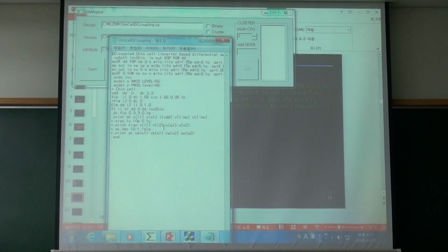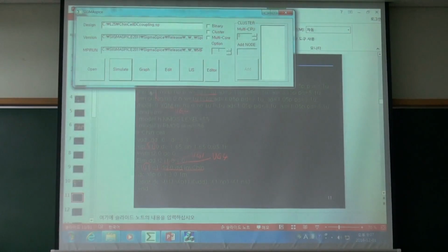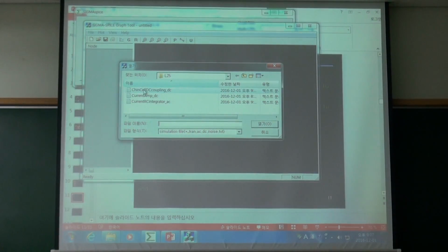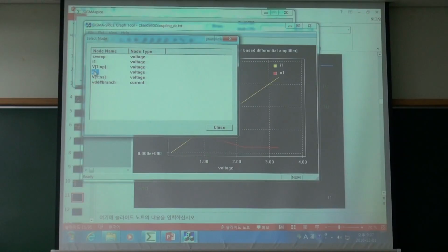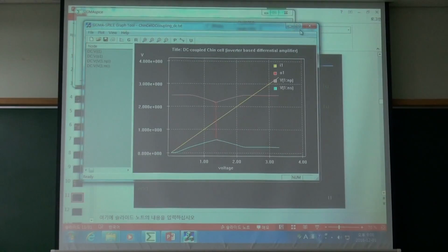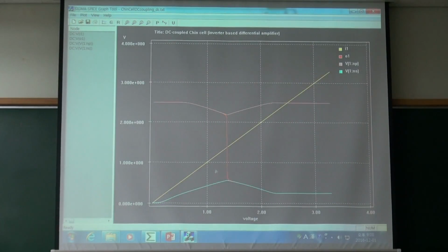Yeah, this thing is the one. So you'll see the same netlist here. I will sweep the input from 0 to VDD and see what happens. I change the input, then what's the output? This is the internal node. You can see this one is from the XP node in subcircuit X1. Okay, so see here. This red one is the output voltage.